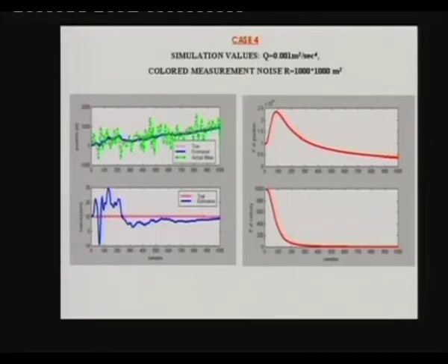This is why, in this case, you should add the noise states also to the Kalman filter, extend the states and then reformulate the problem such that the noise states will also be estimated, then your actual system state estimation will become white and flat again, okay.